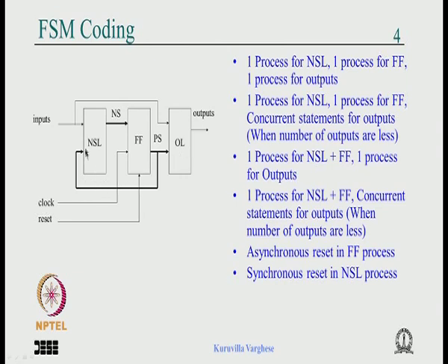We also said that you can combine these two in a single process, because in VHDL you can specify a set of registers with the preceding logic in a single process. So that can be done. In that case you have a process for these 2 blocks together, and a process or a set of concurrent statements for output logic, and you can include the asynchronous reset here along with the flip flop. If it is synchronous reset, it is included here, and when you combine both together there is an issue. We have discussed that; I will just throw light on it.